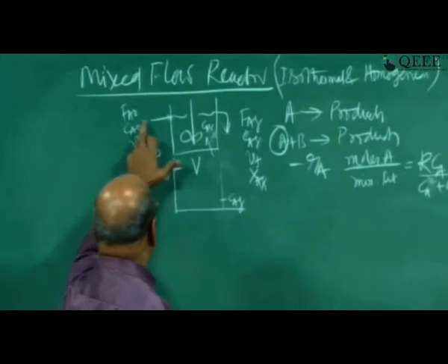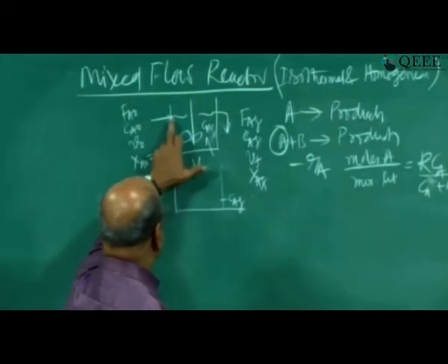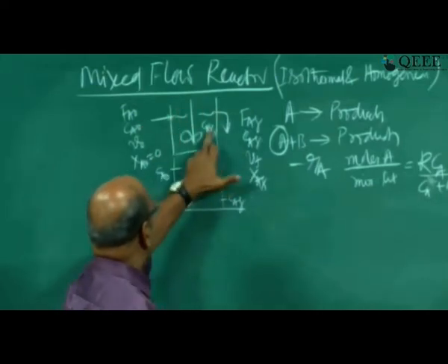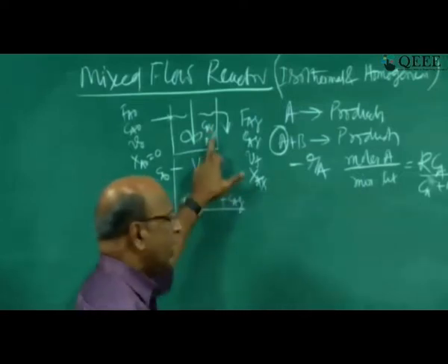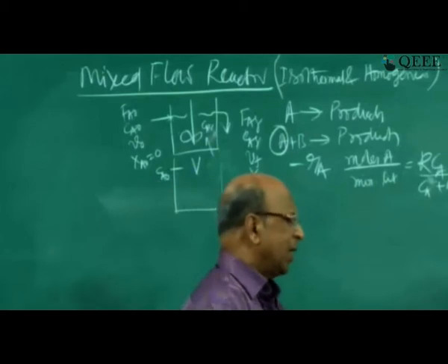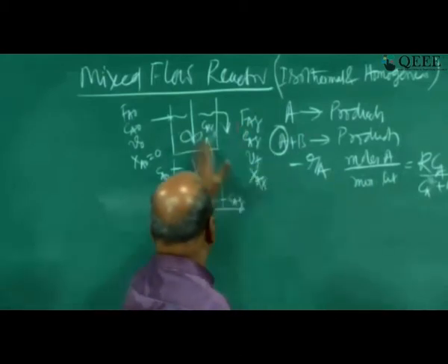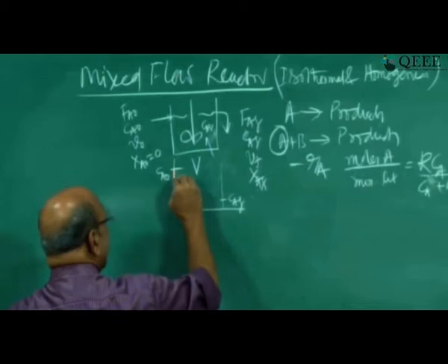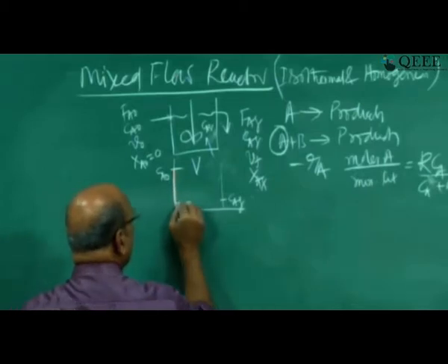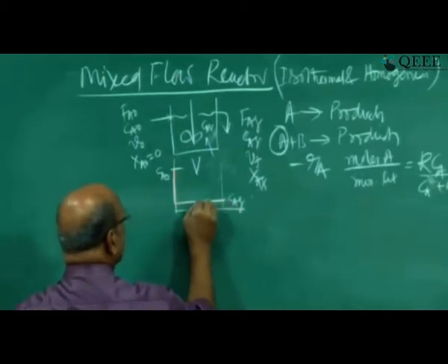So with reaction, now when you have CA0 entering, it is dispersed here, and you get some average concentration CIF depending on the conditions, depending on the concentrations, depending on the conversions, all that, you will get one concentration. That is why the profile will be suddenly going down and then maintaining the same concentration throughout.